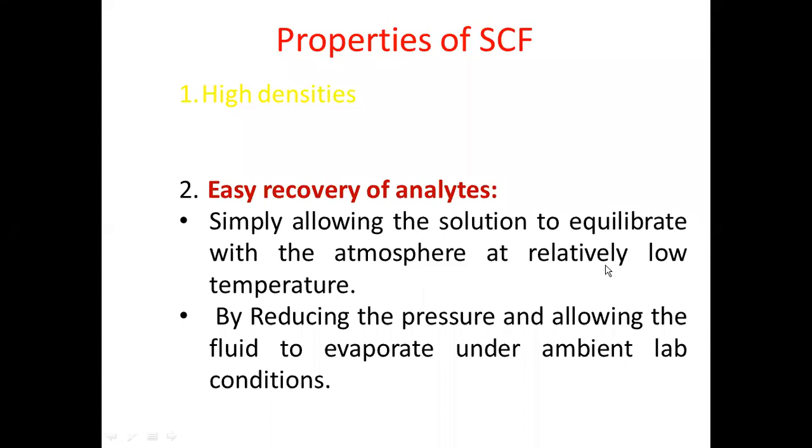So we have adjusted the temperature above its critical point, and commonly the pressure has been adjusted to above its critical point. If you disturb that critical pressure and critical temperature, the supercritical fluid state will be destroyed. The carbon dioxide will escape into the atmosphere, so that if you have a collector flask under ambient temperature, the collector flask will have the analyte.